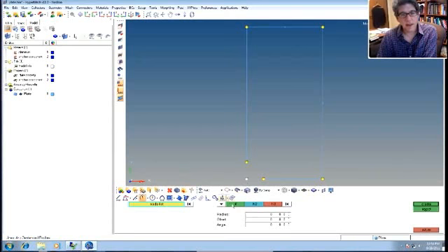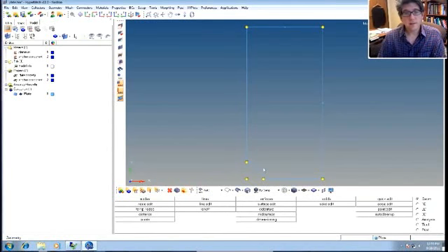And then this next one says, well, an arc has to lie in a plane, so you have to define the plane that it lies in. So we're going to put it in the XY plane. So you have to define a normal vector to that plane. That's going to be the z-axis. And now you can type in the radius. We know the radius is 2. And then the angle is the angle of the arc. I think you can just put 90. Let's see how that works. And it did it. If you get an arc over here, you'll have to put the offset angle, I believe. But that one happens to work. All right, so there we have the lines and the arcs.